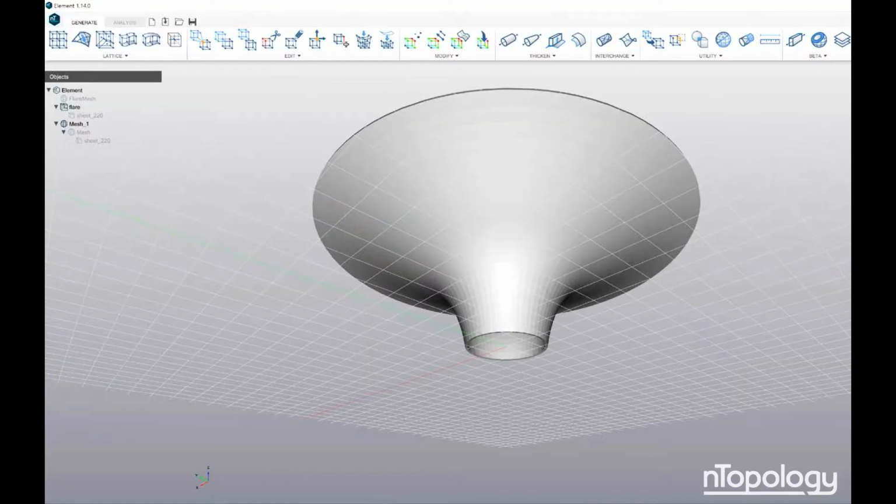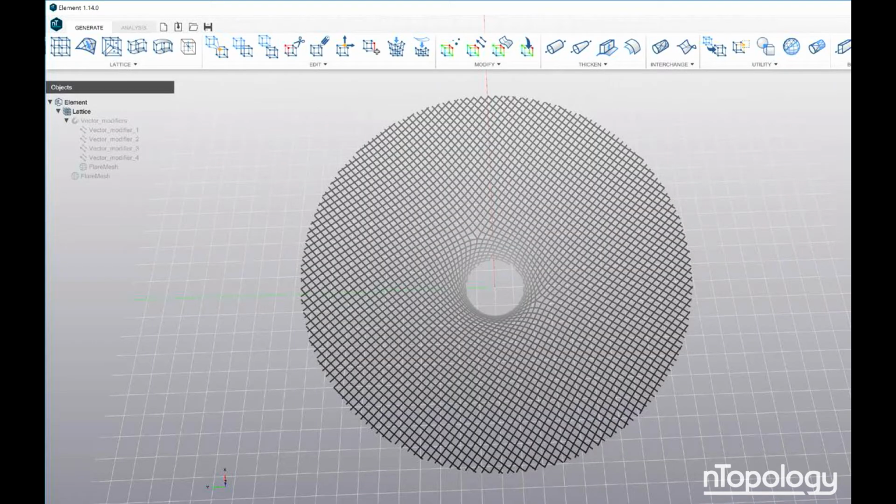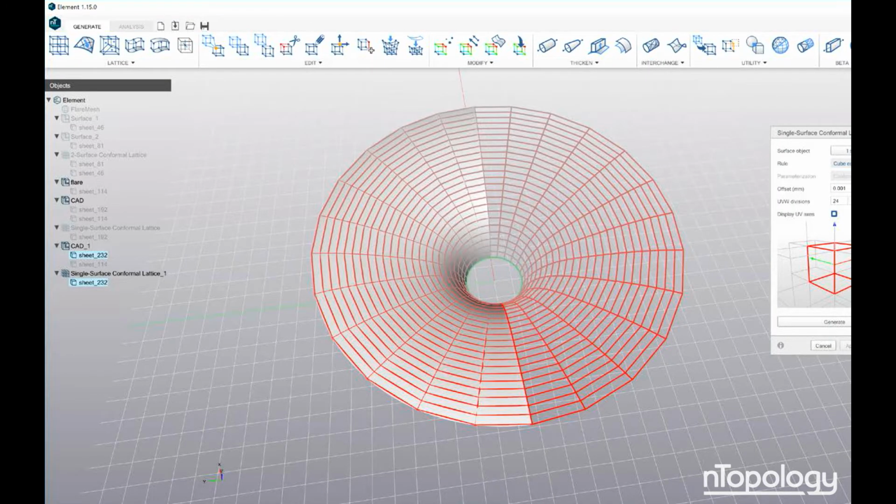And here's another simple flange. If I'm going to make ribs on this flange, there are a couple of ways we can do that, right? The first one would be to just cover the surface and trim the edges. And so you get this pattern that gets cut off on the edges. It's not so nice, right? So maybe as an alternative, you would want to make a conformal structure. In this case, you can take the surface parametrization, map that surface from 3D to a plane, and build the ribs that way.